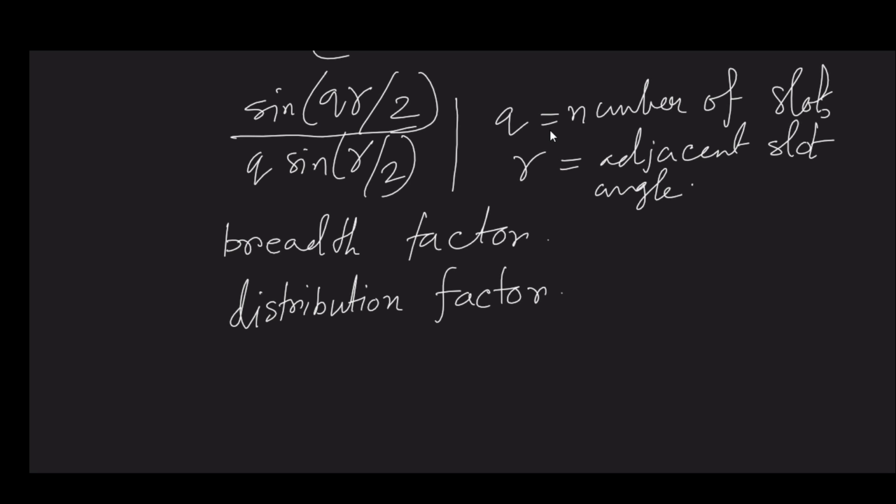your flux density waveform. And flux density waveforms are quite often non-sinusoidal, half wave symmetrical. In addition, they satisfy the Dirichlet condition, so we can represent them in the form of a Fourier series expansion. And if we expand them in Fourier series, then what we will get are higher order harmonics.